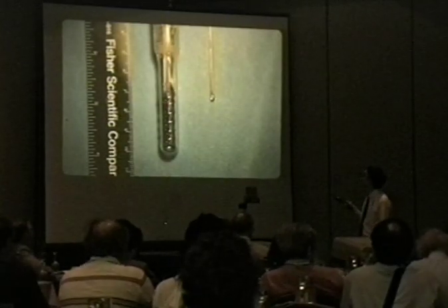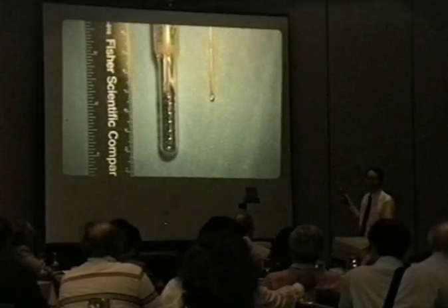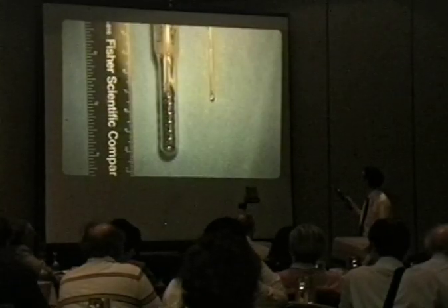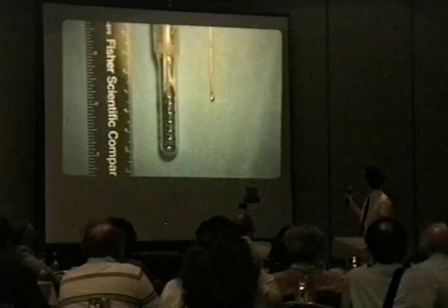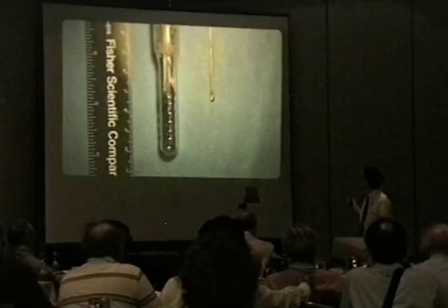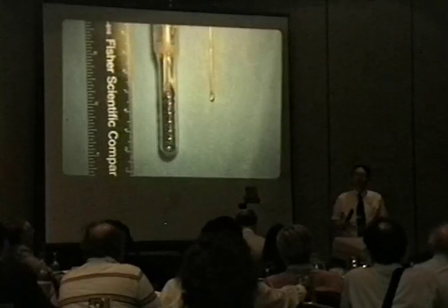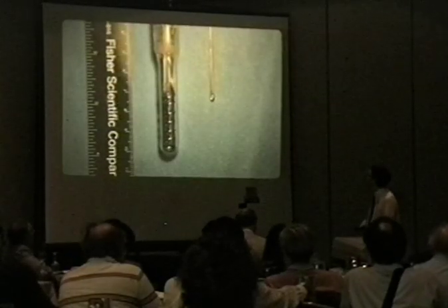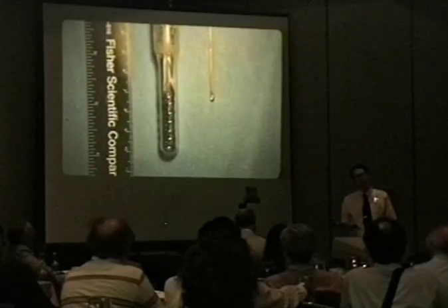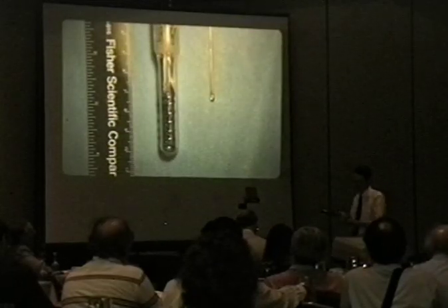My uncertainty in my delta T, which, most of these that I'll show you in a minute are based on temperature differences inside the cell and outside into the bath, is around 0.2 degrees. My calibrations usually run around 3 degrees C per watt, to give you an idea. 3.16 is what I usually get.